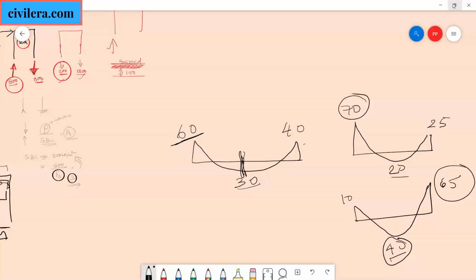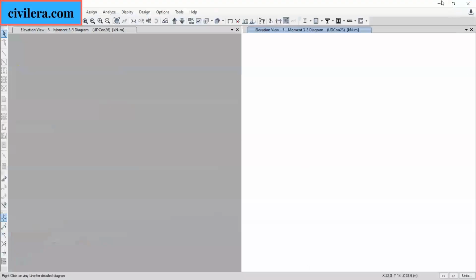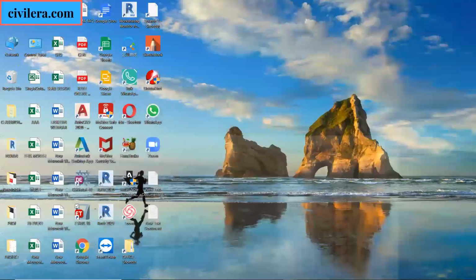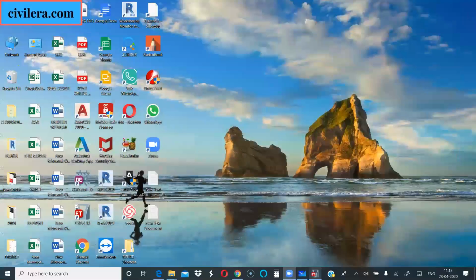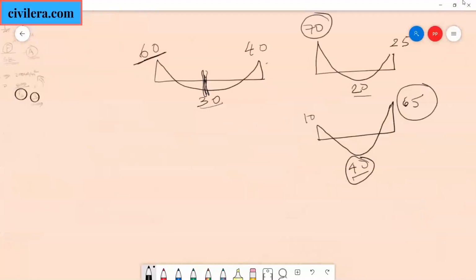If you go by load combinations, you will have to do this 26 times because otherwise we will get confused. You have to write down the bending moment diagram for each combination and then sort out the maximum value. To facilitate this easily, you can always create an envelope of forces. Envelope means nothing but superimposing your bending moment diagrams. Say, instead of writing this three times, take one tracing sheet. I'm telling you an old method.